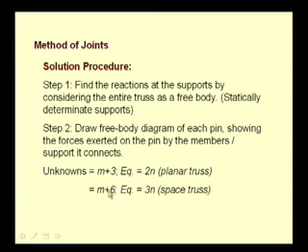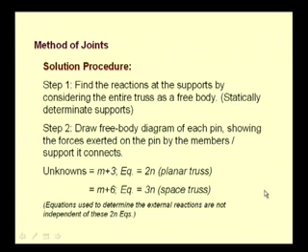So, the number of unknowns, that is the number of members in the truss, plus the number of unknown reactions, that is 6 in case of 3 dimensional trusses, should be equal to 3n for a space truss. Obviously, here we should remember that these equations are not independent of the external equations used for determining the external reactions.